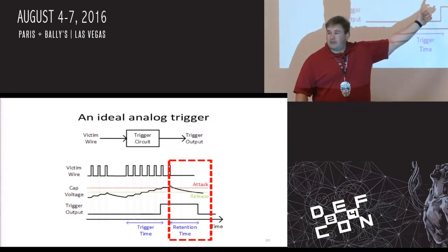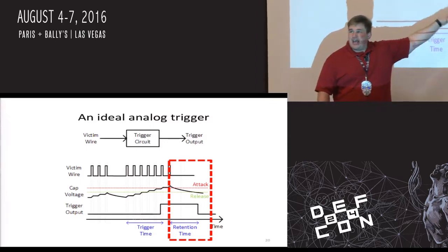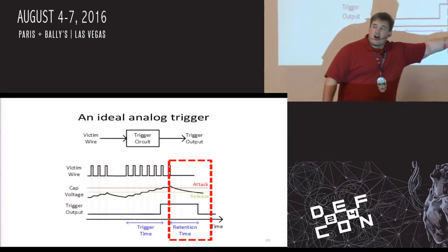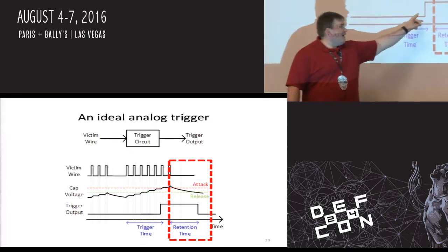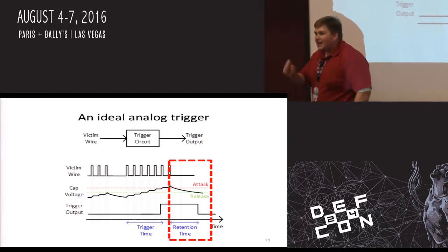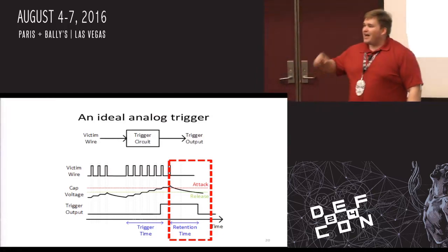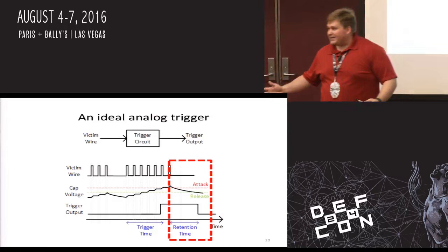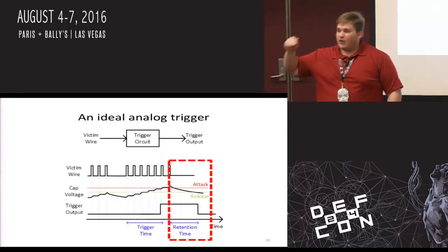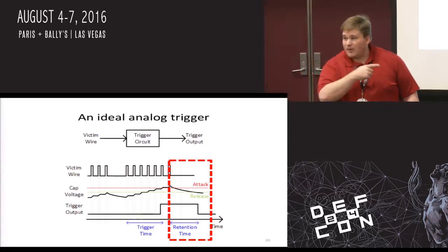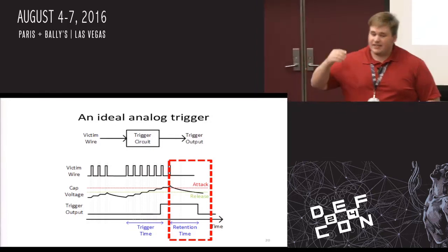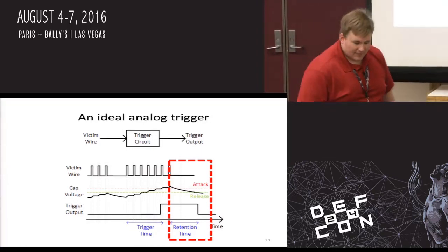And so we'll take advantage again of capacitor leakage and we'll get below that dashed green line and eventually our attack will disable. And this is called the retention time, from when we go on to when we go off. And that's the time frame you have to modify software where you have high enough escalated privilege where you can actually take a hardware attack and make it a software level persistent attack. So the hardware attack is not persistent, but you have a retention time window to make your attack persistent from the hardware level to the software level.